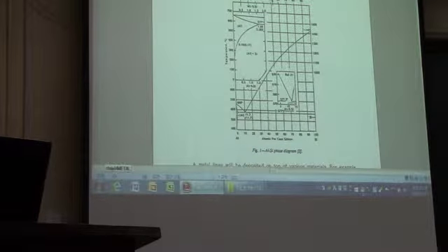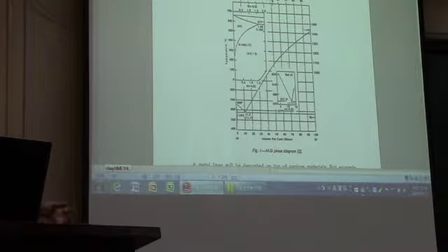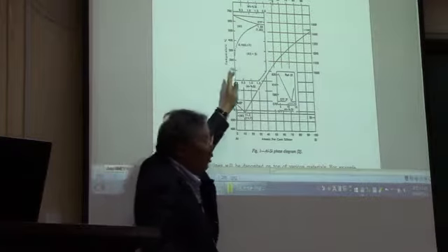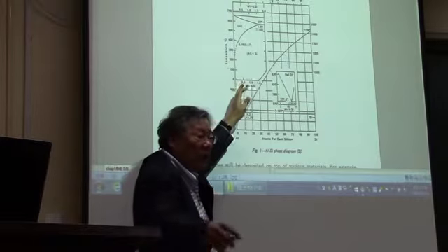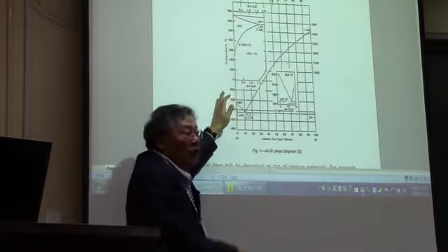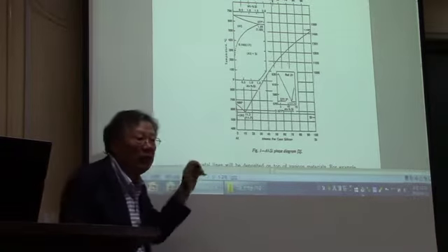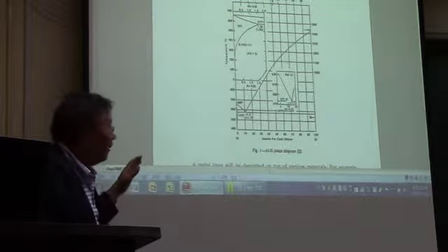Okay? So how can you prevent this? You just put the silicon in the aluminum metal lines beforehand. Okay? And then it already has the solubility limit of silicon in aluminum, so that no more silicon diffusion into aluminum can happen. That's how we can prevent the junction spiking.